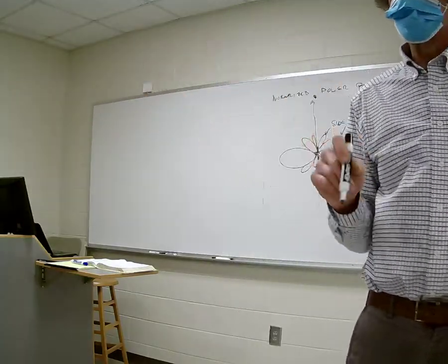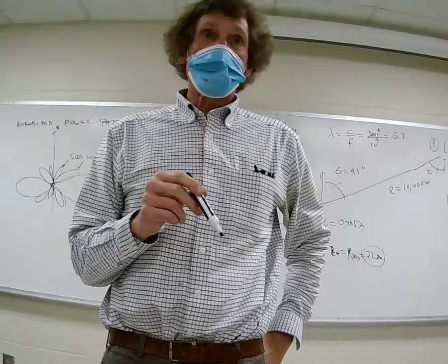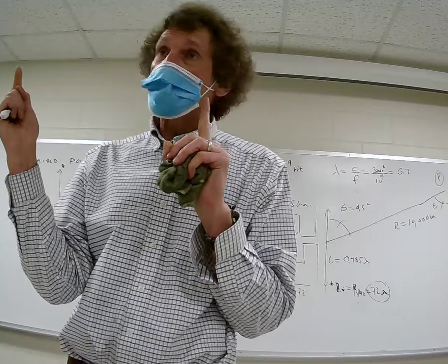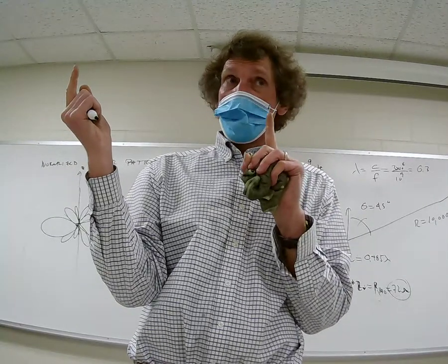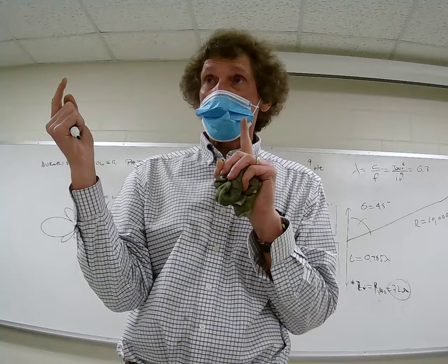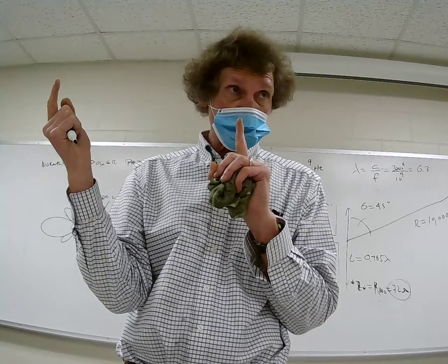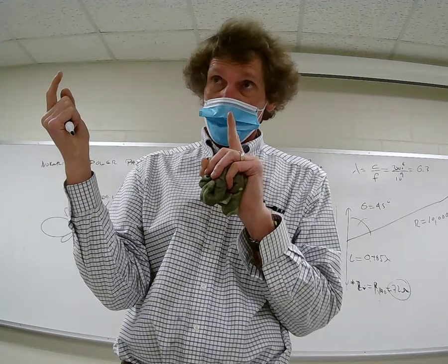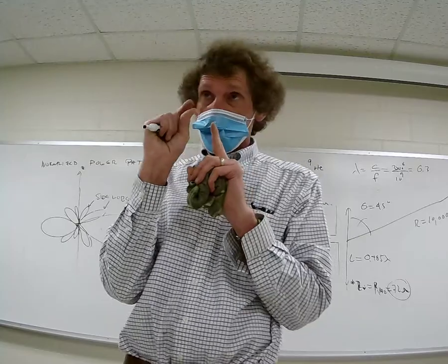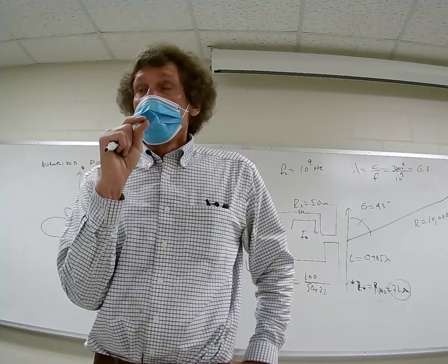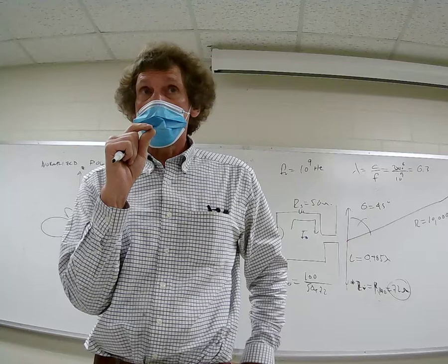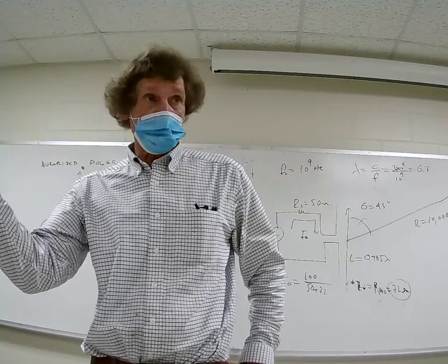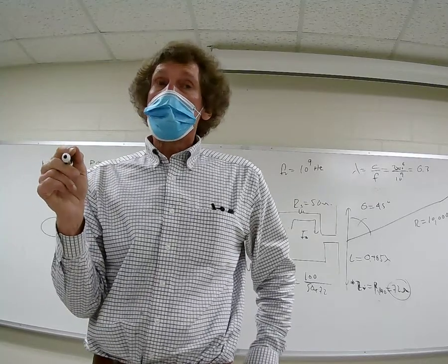I'm also going to say that if I gave you a wire of a certain length and I ask you for the DC resistance and then the AC resistance, you hear me now? You should be able to tell me the difference. That means you have to know how to use skin depth to calculate the change in resistance. You with me? Right? Because skin depth limits the current to the surface of the wire. If I ask, by the way, with the shields, how much power or E field is transmitted, either one, or reflected for that matter.